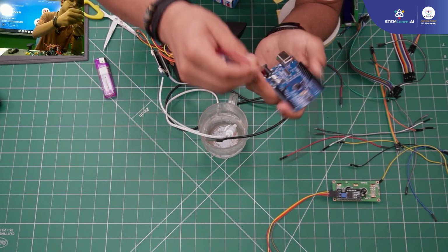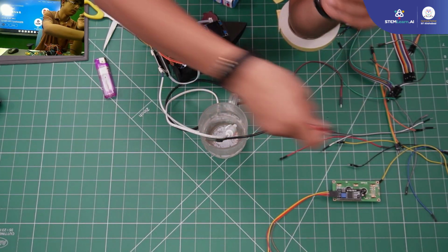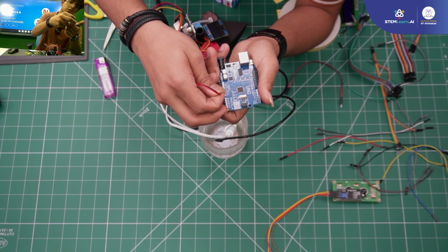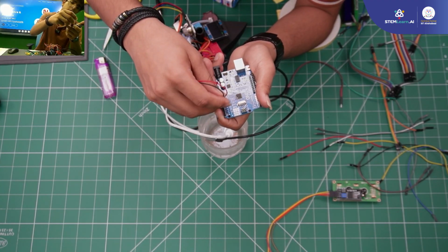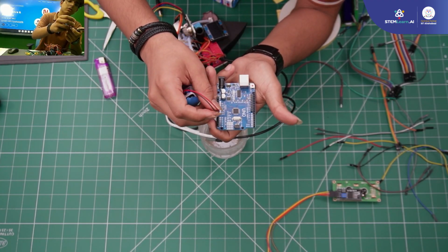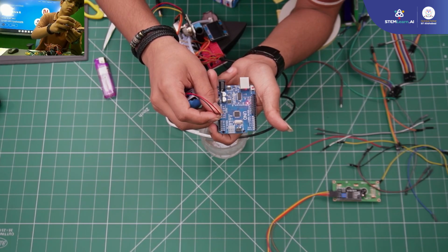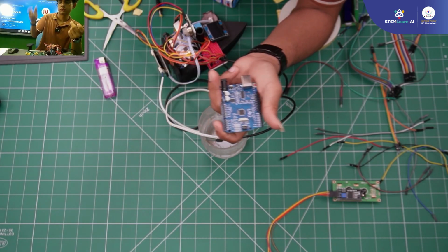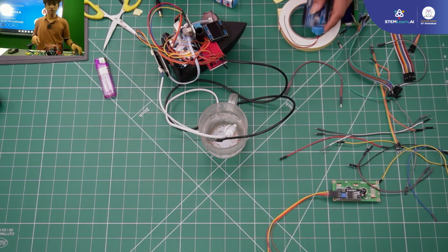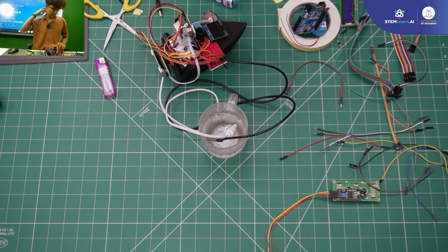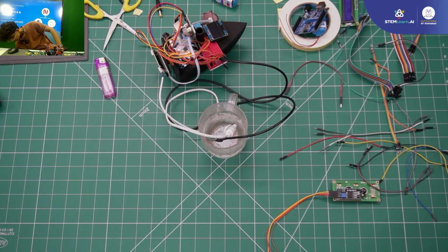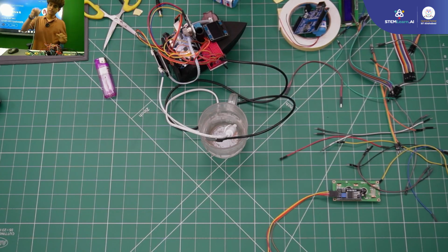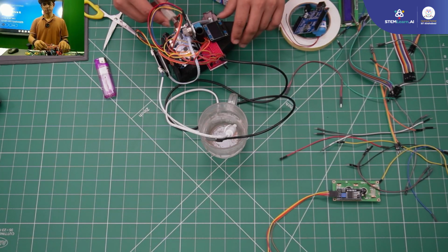Connect this in V-in pin. See, you just need to connect this in V-in. Red one goes in V-in and this one goes in ground. See, it's powered on now, just like that. You can make it independent. As this Arduino is not working anymore, I'll just connect a wire to it, I mean the cable for uploading itself. I'll power it from our laptop.